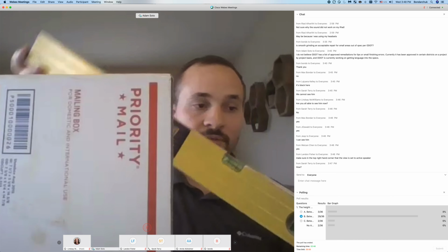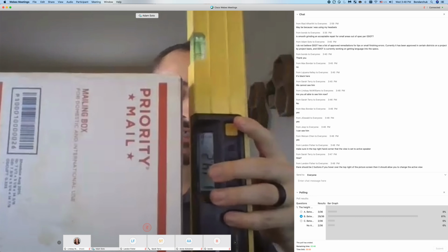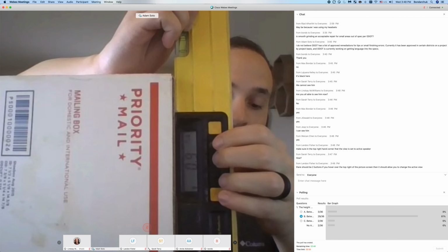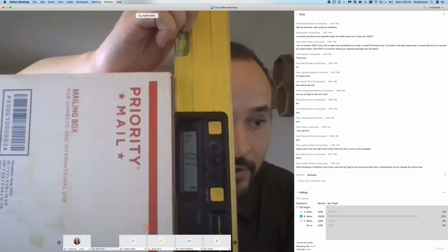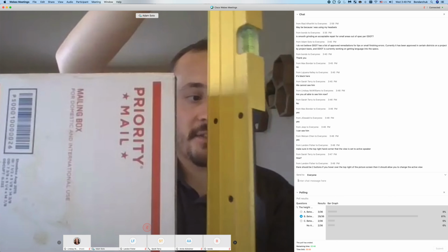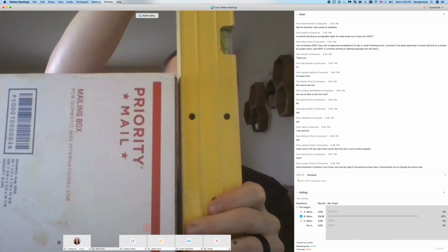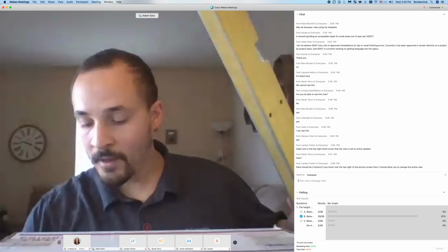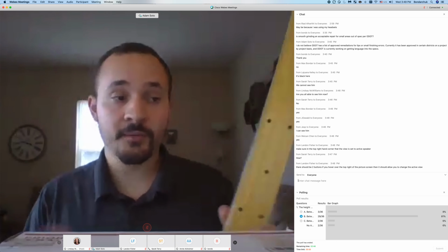Now what we're going to do is we're going to flip it so that the bubble is on top and do the same 2 steps for the rest of the vertical calibration. So we're going to wait for it to settle on a number, press and hold the middle button, and it'll say Cal 1, and it'll begin to flash. And now we're going to twist it 180 degrees, just like that. And then once it flashes the same number 3 times in a row, I'm going to go ahead and press that middle button, and it'll stop flashing. At this point, the level should be calibrated completely.